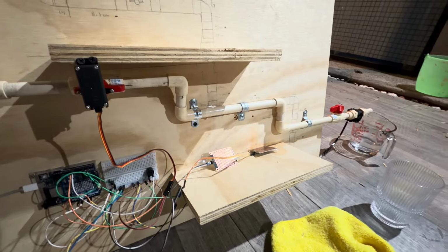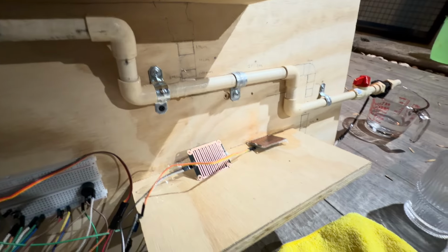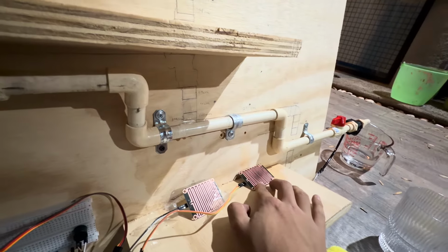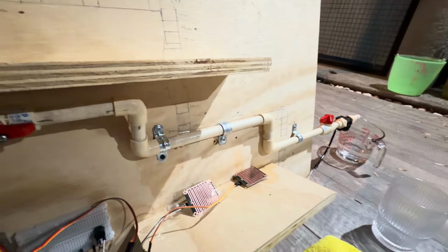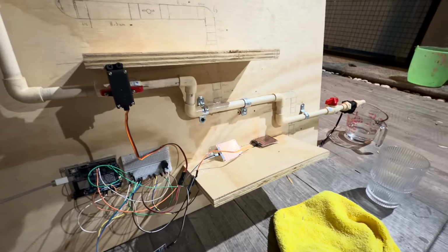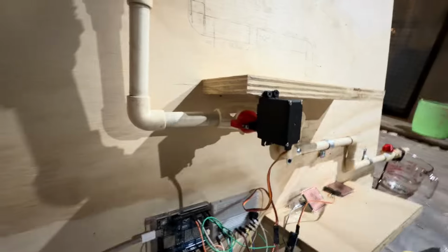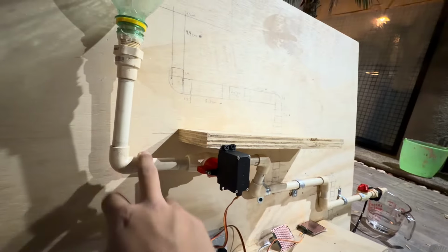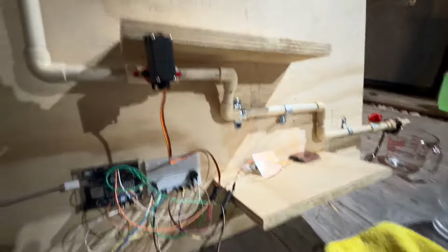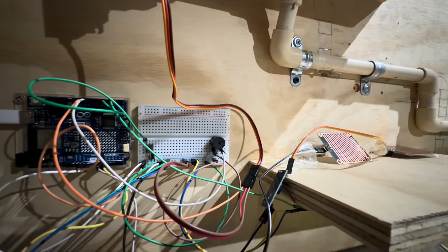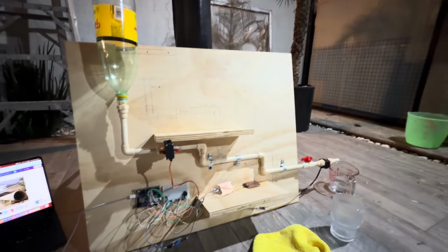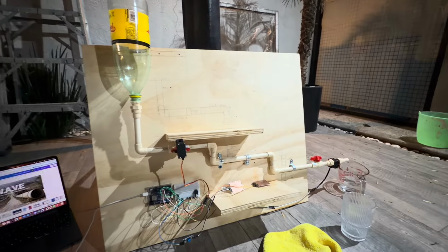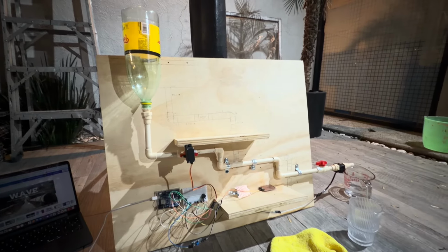Also, if there is a leak, water is going to go out of the pipeline and reach this raindrop sensor. When the raindrop sensor detects water, the automated valve is going to close the valve for the primary network so it doesn't send more water because of the leak. And also the buzzer is going to turn on. So basically, that's the methodology or the process for our project. And we're going to see an example in a few seconds.